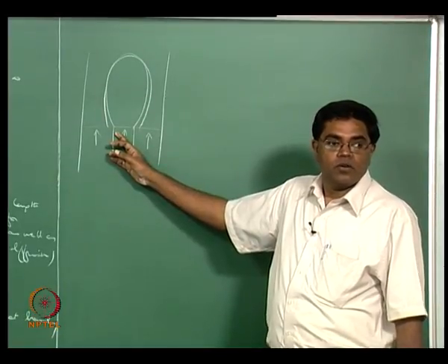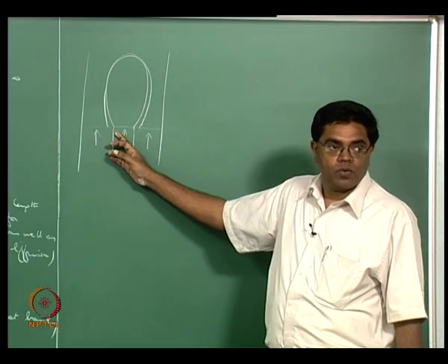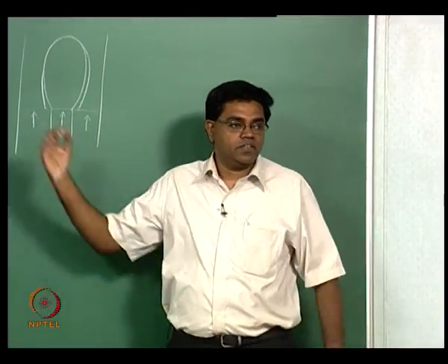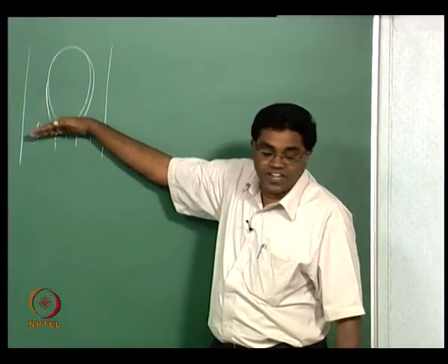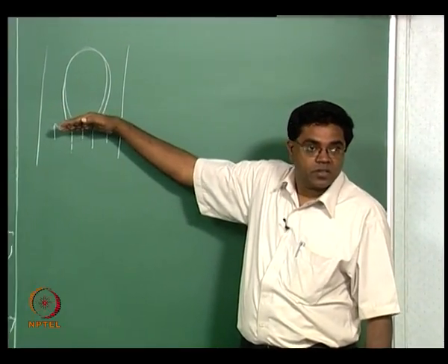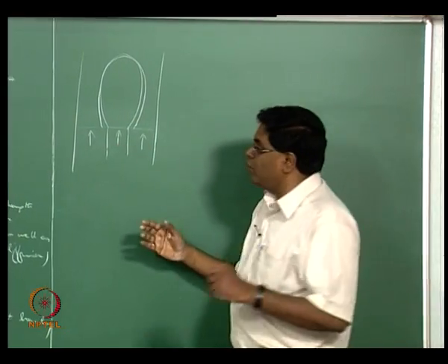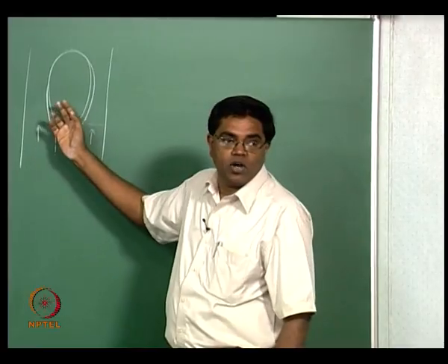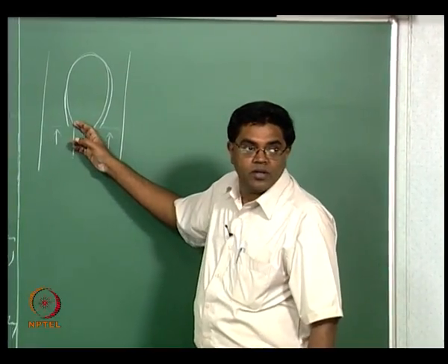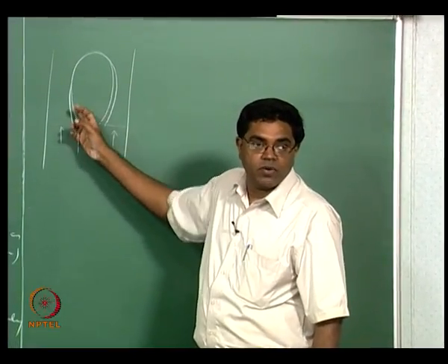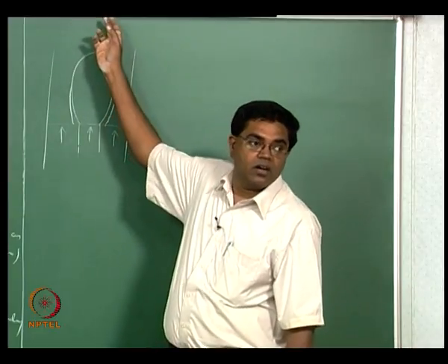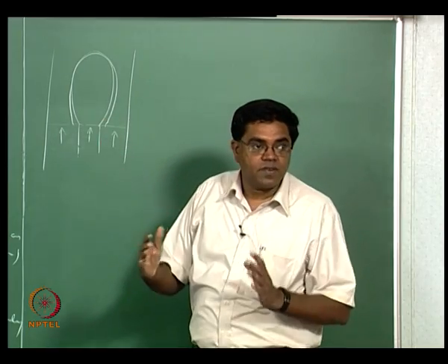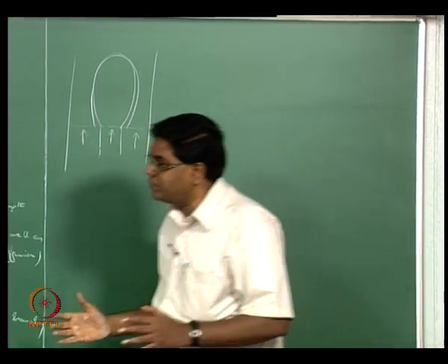Why was it attached to the rim of the burner before? Because we did not permit axial diffusion across the interface, across the inlet, and therefore when the fuel and oxidizer met, the first opportunity at which they could meet was right at the burner lip, and they meet at stoichiometric proportions there and then on in a certain curved manner, and therefore the stoichiometric surface starts from the lip of the burner, like what we have shown here.